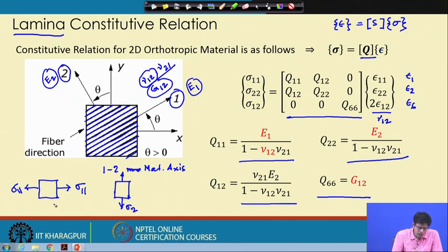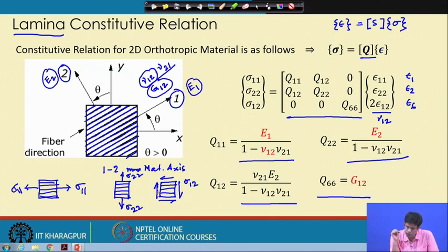2 here. And by the way, this is the fiber axis. Here the fiber axis is here, so we will give the sigma 2 2 in this direction, and another is the pure shear stress, where we will give this. So this gives us sigma 1 2. So this gives us the 4 independent constants, which are E1, E2, nu 1 2 and G1 2.